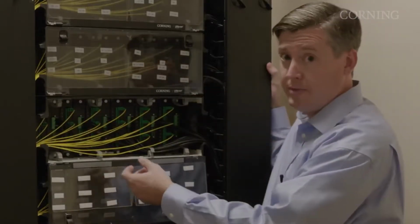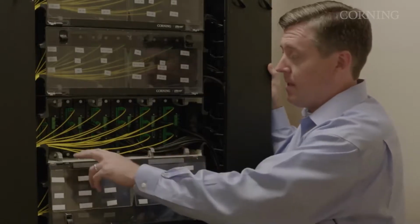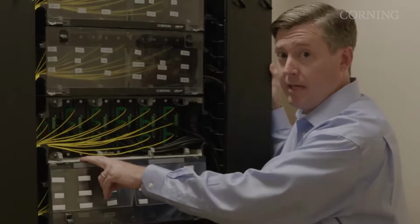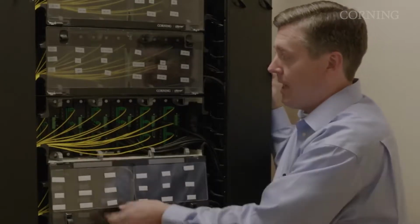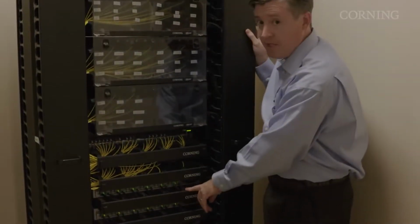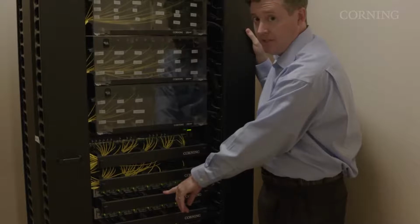The composite cables are coming in, terminating on the back of this housing. Now this housing is my patch point for both the fiber as well as the power, because remember, we're bringing composite cable into each of the rooms. The power is patching into the PSU. So this is where I'm getting my 100-watt circuits, which are feeding the ONTs.